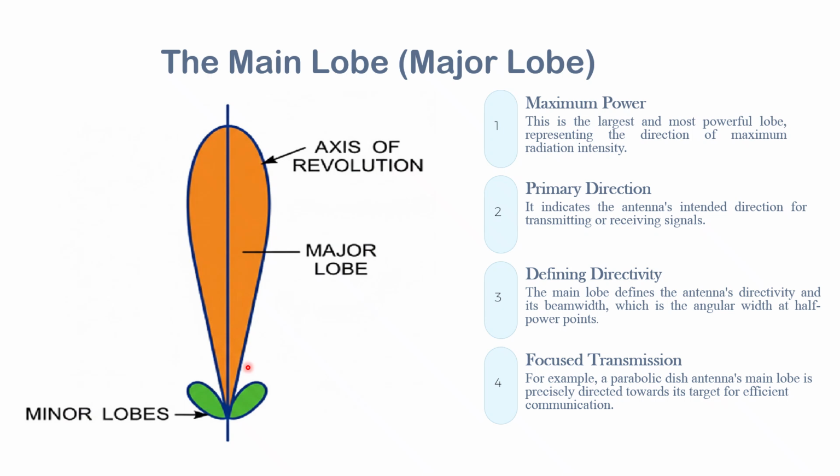We have a classification of antennas: directional antenna, omnidirectional antenna, and isotropic antenna. If it is a directional antenna, the radiation pattern will be maximum in only one particular direction. In the case of the omnidirectional antenna, we have radiation around the antenna in all directions, which means the radiation can be experienced around 360 degrees. But the gain of the antenna does not remain the same around the 360 degrees.